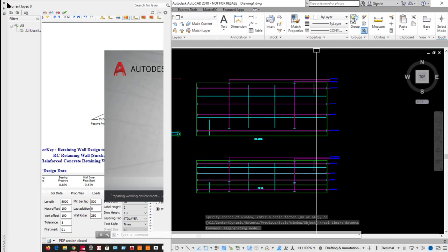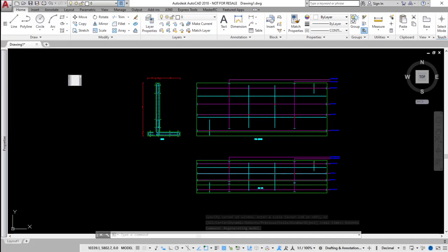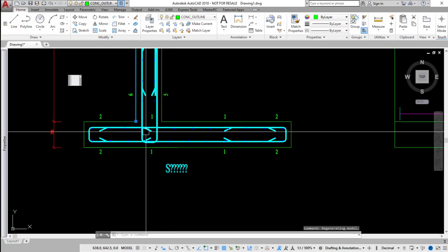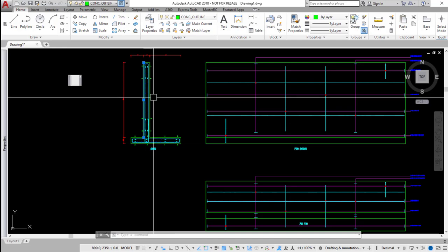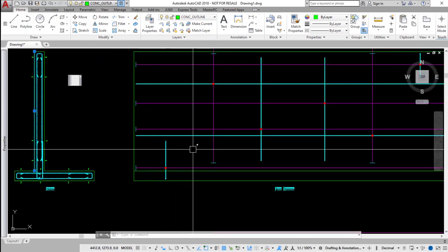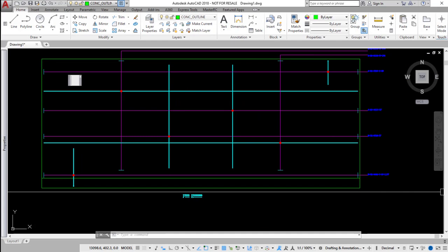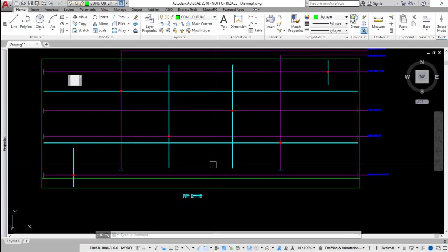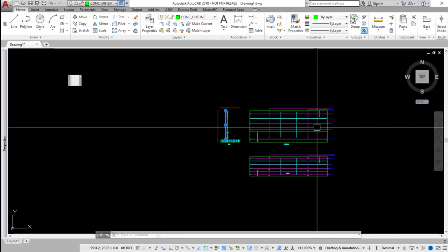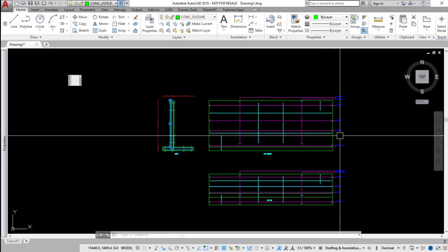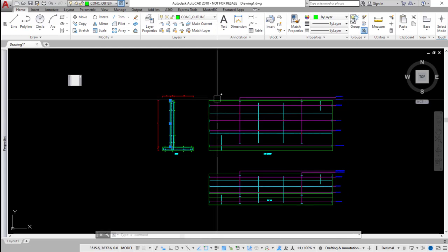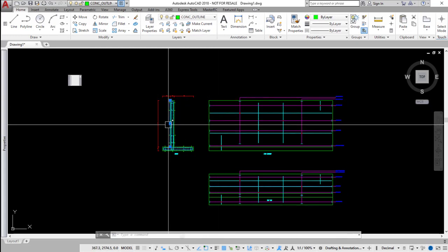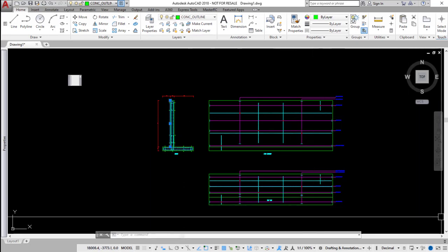We don't need this little CAD layer thing, so there you go. There's your details coming up, and it's probably the thickness of one of these for the bars is too small, is what the problem is. And then there's your starter bars and your main bars. Now at this moment in time, the main steel and the starter bars are all the same. Certainly what you can do is curtail your reinforcement to have half of it stopping short, and as long as you're above the point at which it's no longer required, or only half of it is required, that will be okay again.